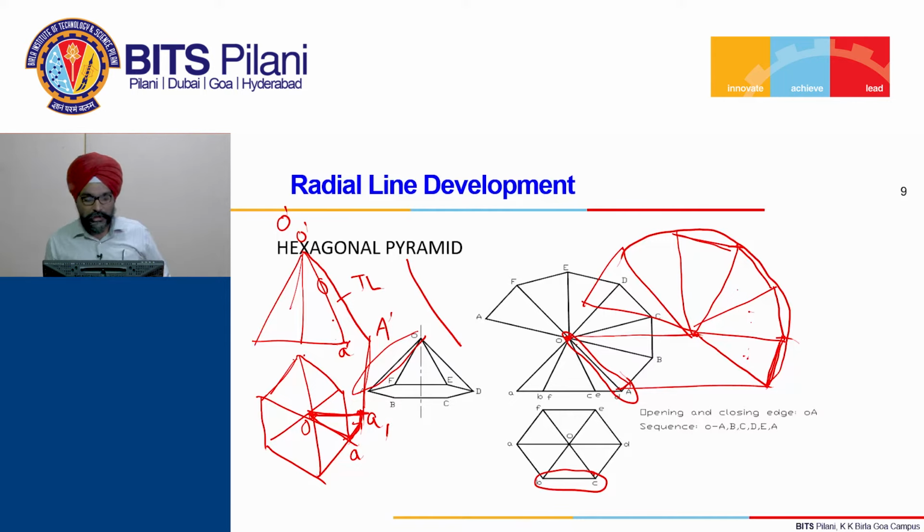In the earlier orientation, the edge which we had was itself the true length. The reason was that this particular edge corresponding to OD was parallel to the XY line. If it is not parallel to the XY line, then this separate step you have to carry out. This has been explained in several other videos using AutoCAD also, so you can refer to those videos.